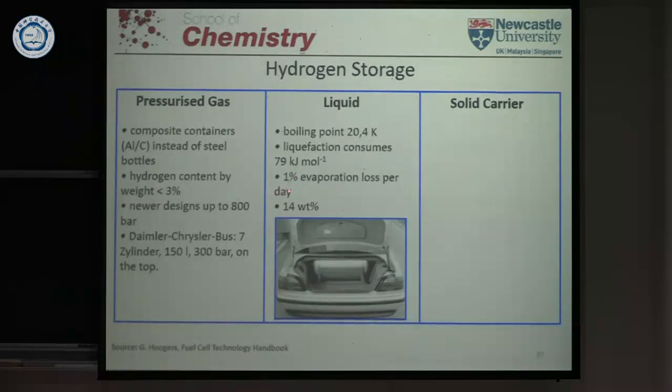So it's not good when you have a car with liquid hydrogen, and you park this for, let's say, a month and a half because you go on vacation, and you come back, then half of your tank is empty. You wouldn't like that idea. But you see, the weight percentage is much higher than with the gaseous, because the liquid state contains more hydrogen. But the overall energy balance of liquid hydrogen is not that good, as I said, because of liquefaction and the boil off, and that makes a problem.